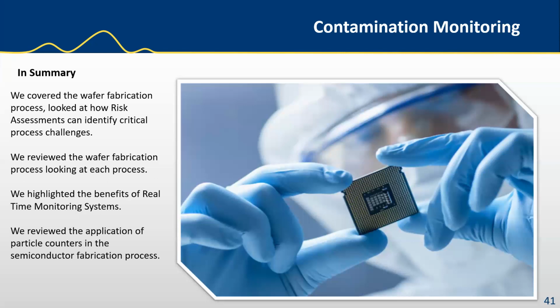So you've always got your data. With mirrored databases, if the main computer fails, the secondary will automatically take over data collection. And it provides you with uninterrupted data collection and alarming of out of specification conditions. So the redundancy of the real-time monitoring system is critical.